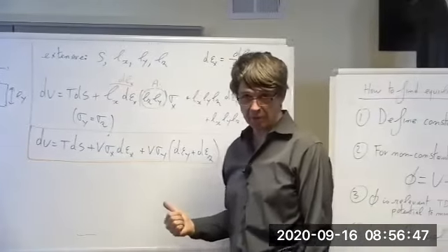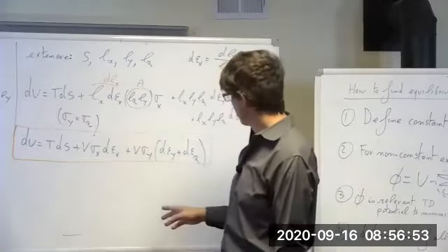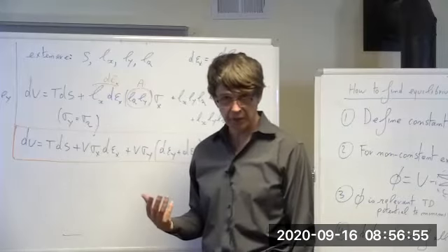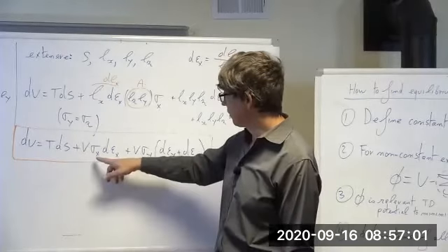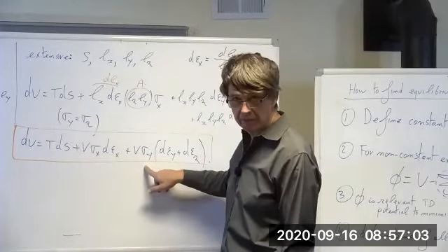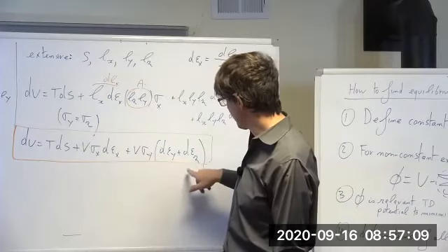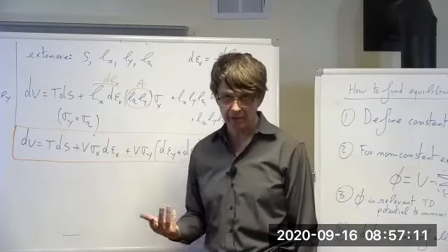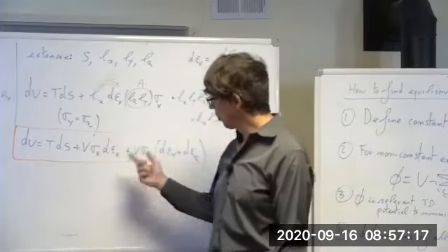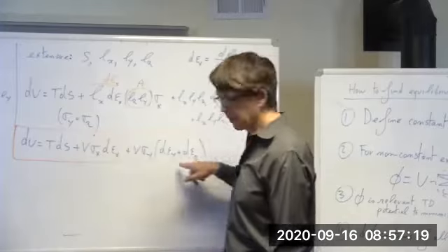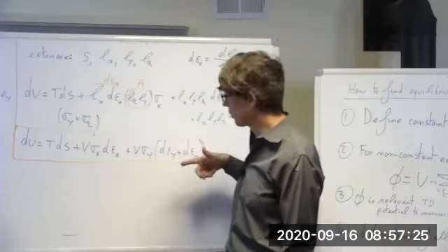We could have just made this up, right? Because I haven't assumed anything about the boundary conditions, but look at this, right? Do you remember in the first or the second lecture where we calculated mechanical work? If sigma x and sigma y were the same, if I were in a pressure field, then I just get the epsilon x plus the epsilon y plus the epsilon z times the volume, and that's dV, right? It's the diagonal elements of the strain tensor times volume, so I get dV. So basically, this is a complicated version of what becomes pdV in an isotropic system under pressure, right?